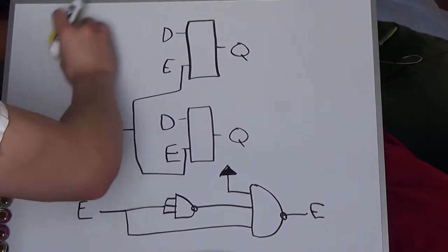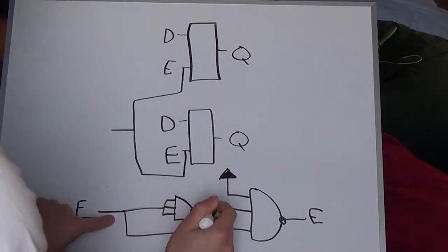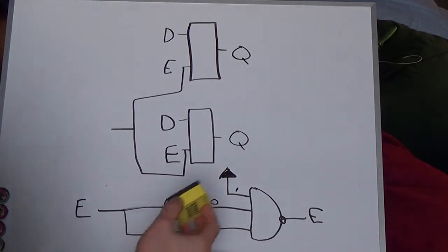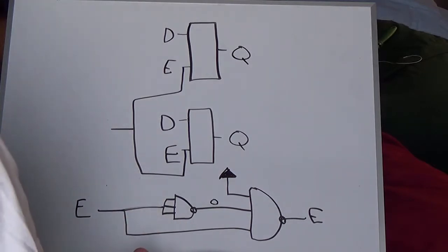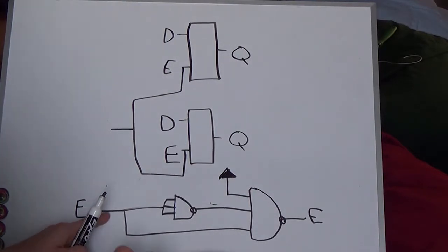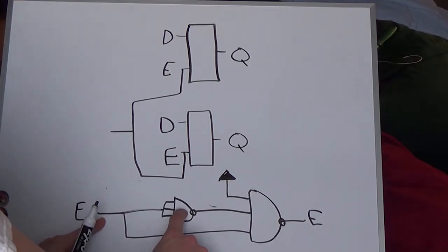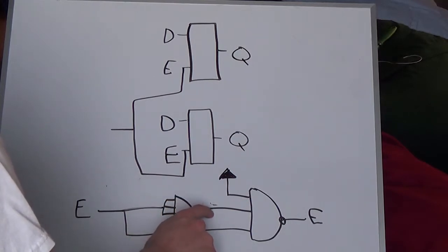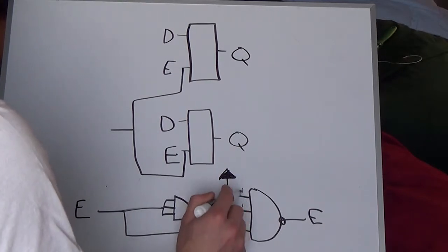Well, what'll happen is initially when this is low, this here will be high, and so this will be a 0, this is a 1. So basically, in order to make a 3-input NAND gate a 2-input NAND gate, you just pull one of its inputs high, and it'll function as if it were just a 2-input NAND gate. So when I pulse this signal here high, this signal will go high right away, and because this logic gate has a certain propagation delay, a certain amount of time it's going to take for this to switch from high to low, for about 6 nanoseconds you'll see all 3 of these inputs high.